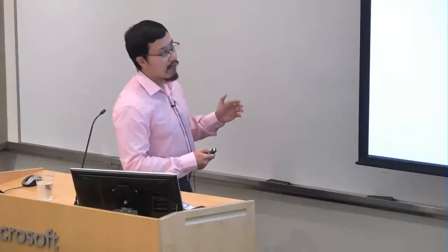And on the other side, we have the accelerometer and the magnetometer. These two are trying to estimate the orientation based on a unified field, which is the gravity field for the accelerometer and the magnetic field for the magnetometer. The solution is not always unique, so we need to use a gradient descent optimization to get the estimation. There is some math here, which I'm not going to dig into deeply. The take-home message is that we can estimate the quaternion of the orientation by gradient descent, by playing with this convergence term, which guarantees that we get the optimal solution.